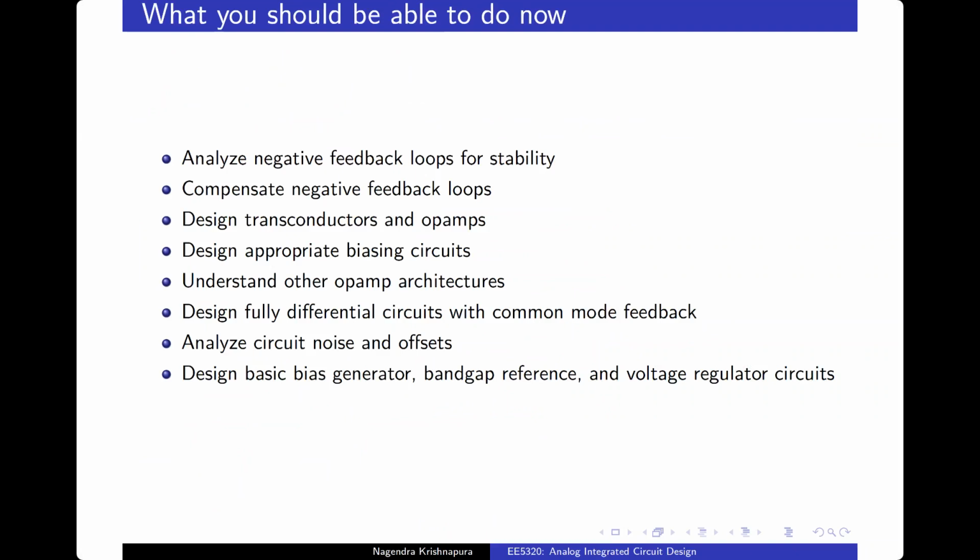No, no, you can't make that floating current source, right? That's a representation that simply says that the same current is flowing through the diode connected transistor and this diode connected transistor. If you have two separate current sources, the same thing will happen. There's no change at all. If you have the same currents, why will they be different? If they have the same current value, they'll not be different, right? Here you are using an ideal current source. If you use an ideal current source, one or two, what difference will it make? That's what I'm saying. There is no floating current source, right? You can't do that. So that's just a representation of current flowing there. That's all.